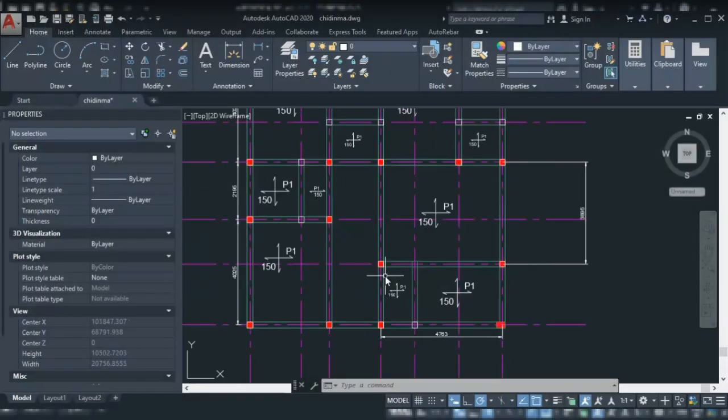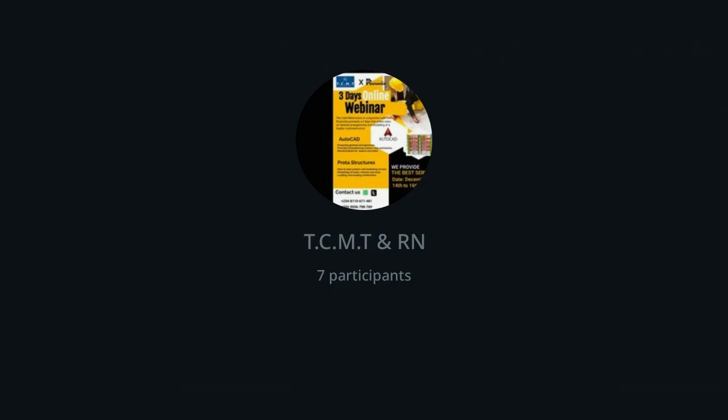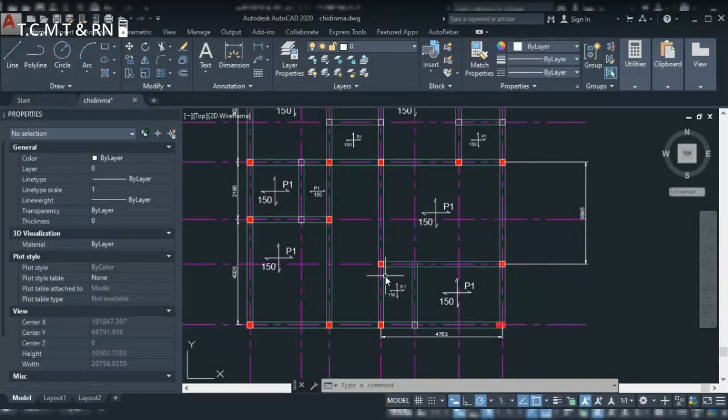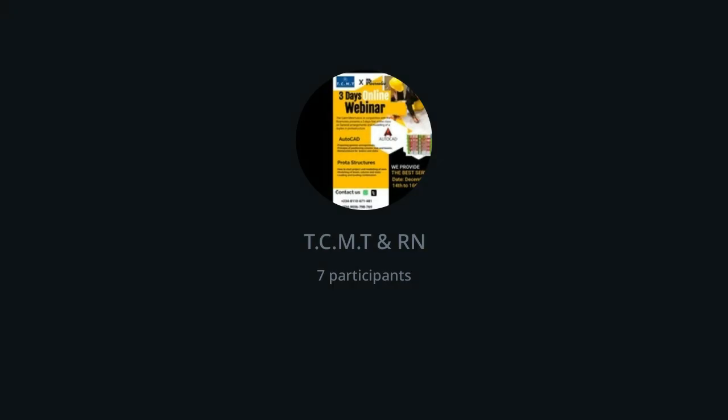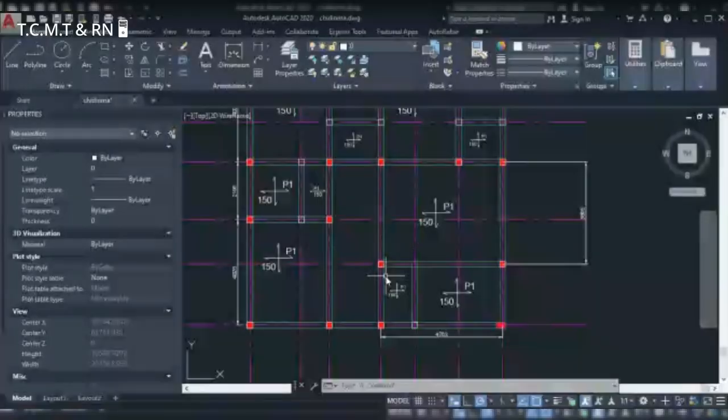Okay, so what we calculated, because what you normally represent on your ground floor plan, is the going, not the riser. What you represent when you are looking at your building from the top is the going, not the riser. So we calculated the total length for the going to be 3 meters, right?